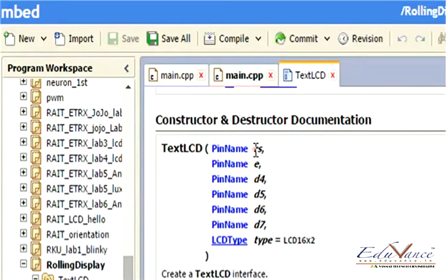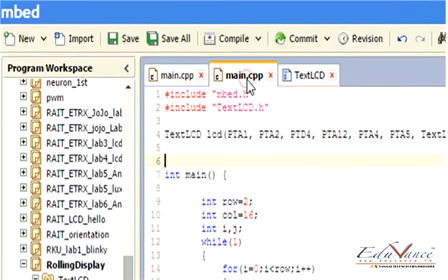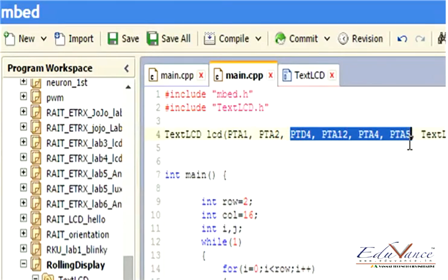So we have the first pin RS, second one is enable, then the remaining 4 pins are data pins, which is D4 to D7, since we are sending data to the higher byte. Come back to the main code and check. This is PTA1, which is RS. That is what we've defined earlier, that is, I defined in the video explanation. Then we have our enable. Then we have the 4 data.